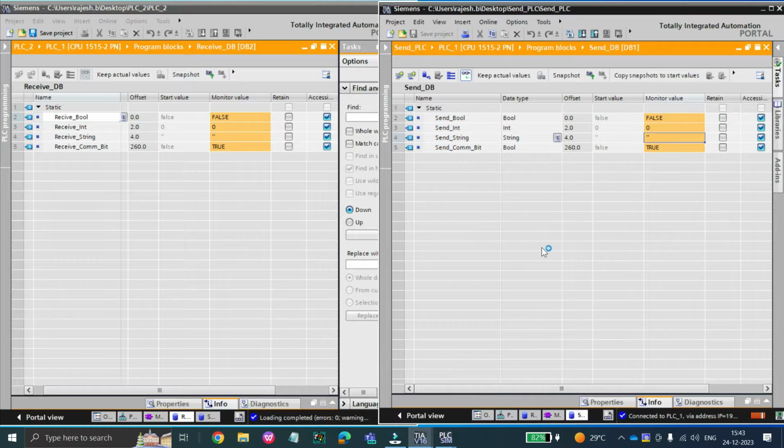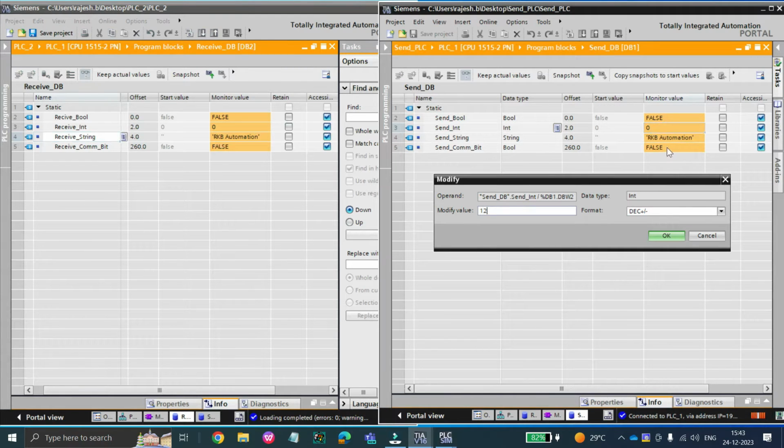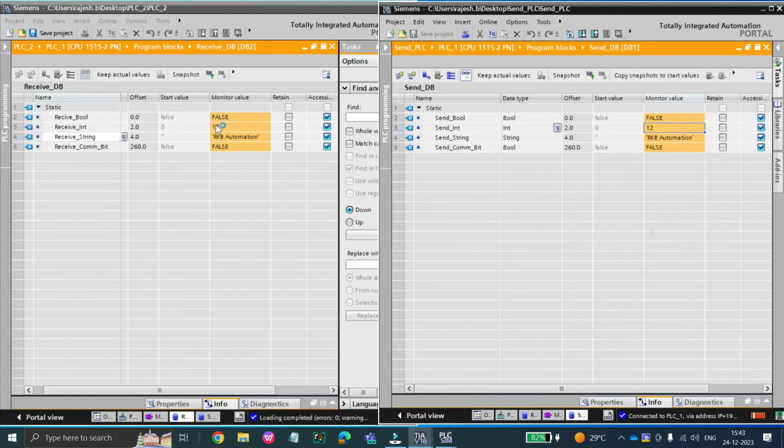We are going to discuss today how to communicate between two PLCs through the open user communication protocol called T-Send Compact and T-Receive Compact, where we are using the protocol Ethernet TCP/IP. I know there are several methods, such as Put and Get methods, but there you have the limitation of tags.